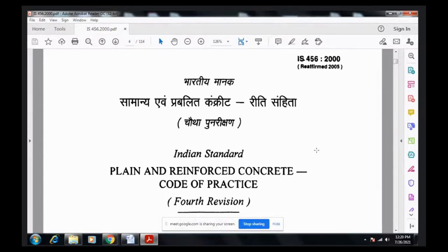Similarly, you have to also recommend the diameter of these stirrups, the rings. Whether it is 8 millimeter or 10 millimeter, you have to recommend it. That is also after some calculations based on structural mechanics. And also with IS 456, this particular code, you have to finally say that yes, the diameter of the stirrup is 8 millimeter, and the distance between stirrups, suppose, 200 millimeter center.